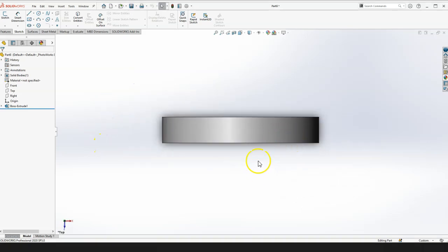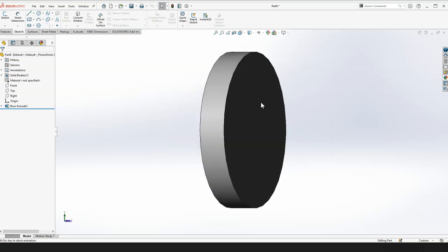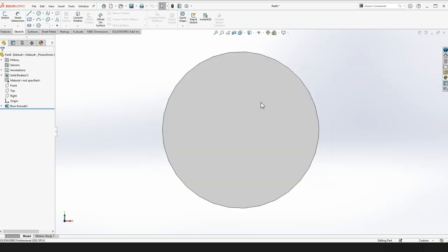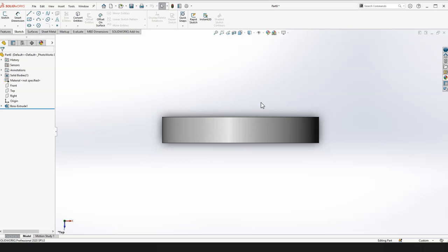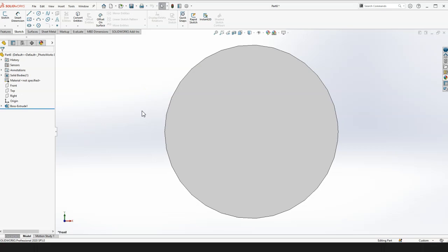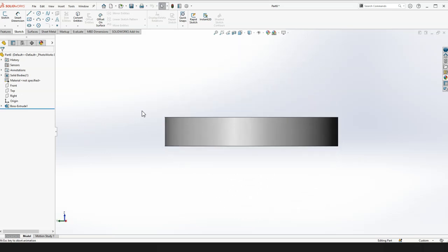Let's say I want to orient that, like spin it 90 degrees. What you can do is hold down shift and press the up arrow. It'll give you that. Do a right arrow, left arrow, down arrow. This is all while you're holding down shift. And this will come handy when you're trying to look at the planes you're working on or mid plane and that sort of stuff. Yeah, they'll come super handy. Once you do your orientation at one view, then just hold down shift and use the arrow keys to turn 90 degrees in any direction. So yeah, they come super handy there.